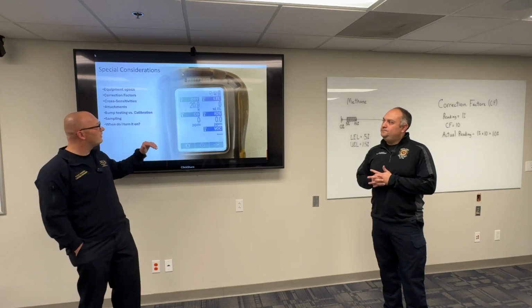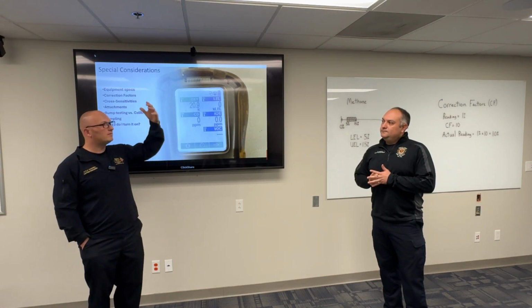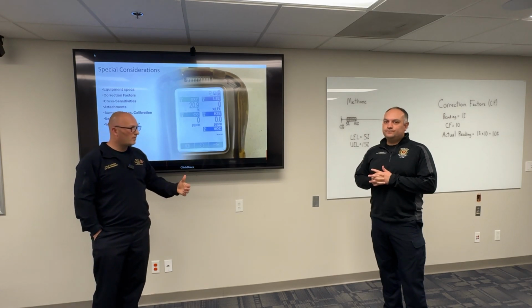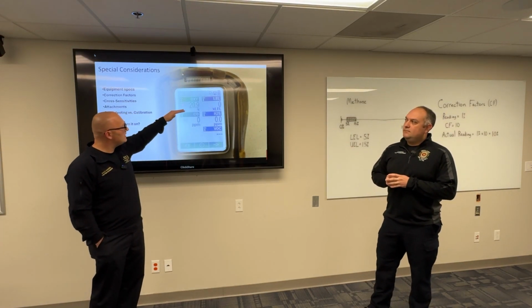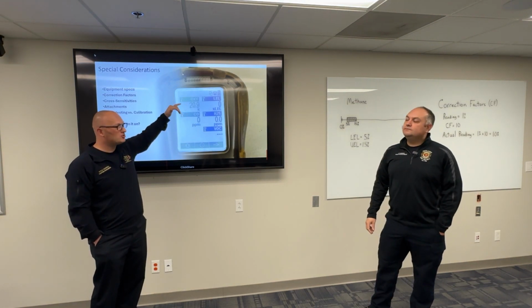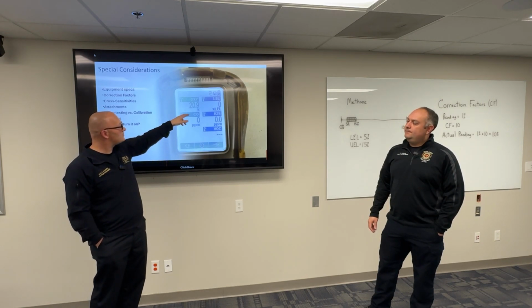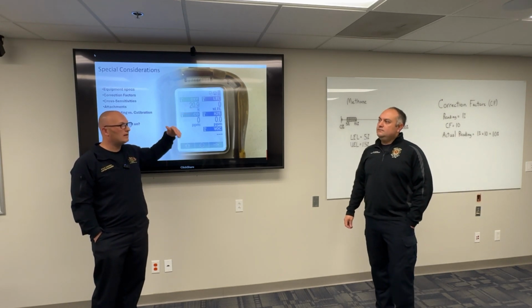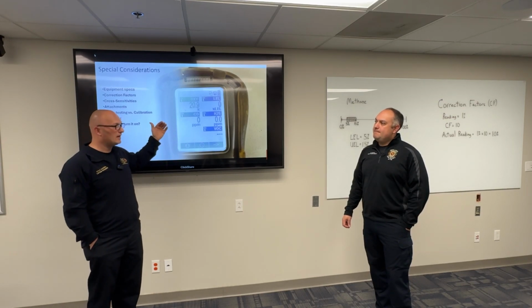And then, like we mentioned earlier, when I'm going into these buildings, I might be on a CO alarm going off, but I'm going to take my time and go through every level, like Nick said. As I walk a little bit more, stop and go again, but look at each thing. I need to pay attention to what my oxygen's doing. If my oxygen drops that 1%, I've got something significant going on. If it drops from just 20.9 to 20.8, that's still 5,000 parts of something else in that building other than oxygen.